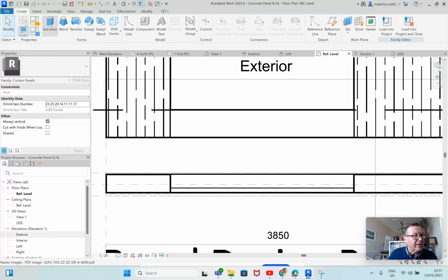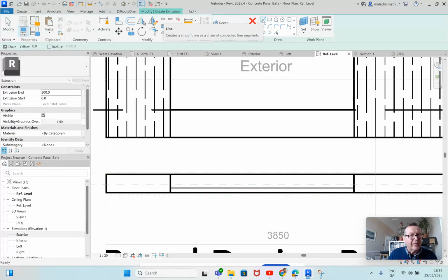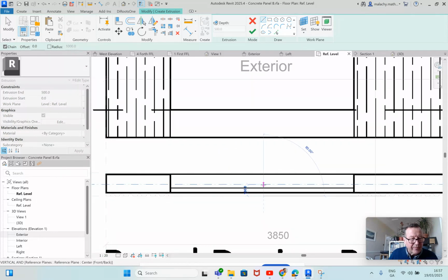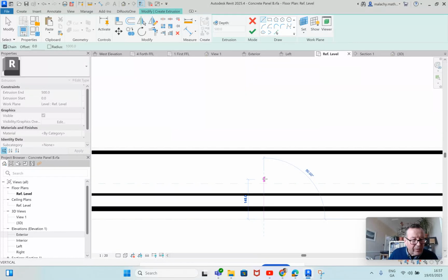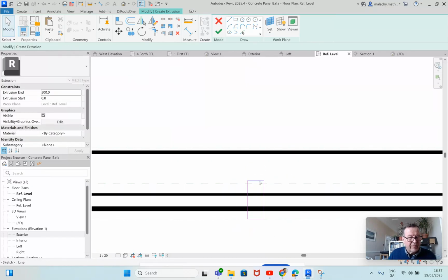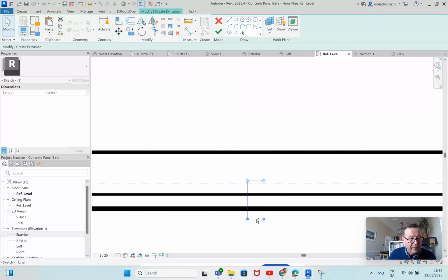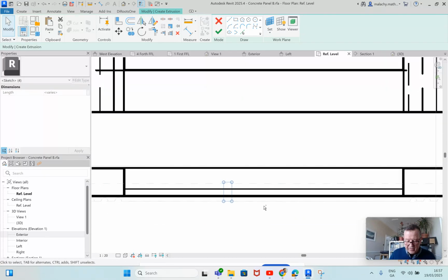Okay. So, create an extrusion, and here. So we're going to go from more or less in the center. I could do it in the center point, but I prefer to do it as a kind of a third across. But anyway, look, so that goes out to 140, wasn't it, by 60. Now, so I can take that and I can just move it over here, just use my arrow keys to position it something like so.